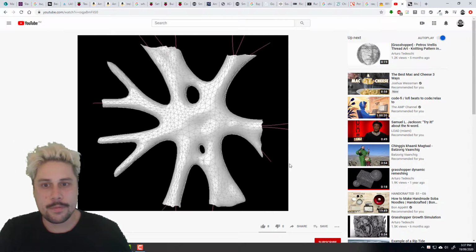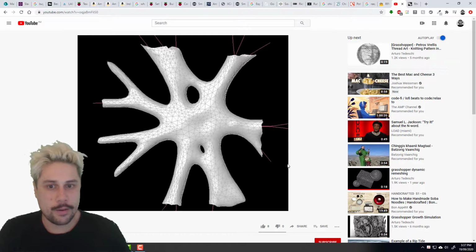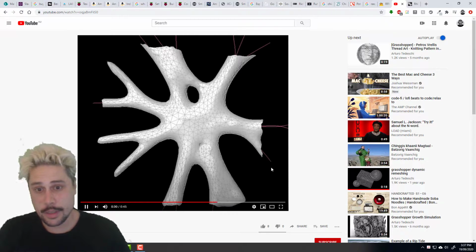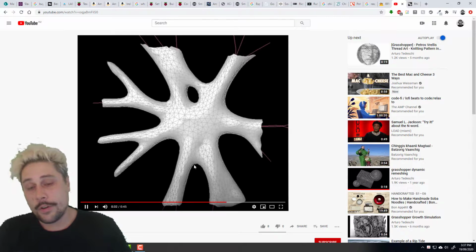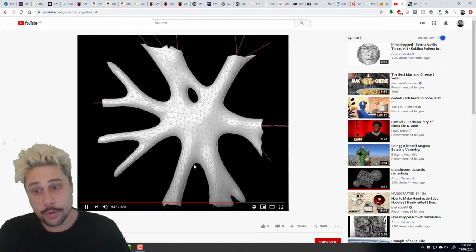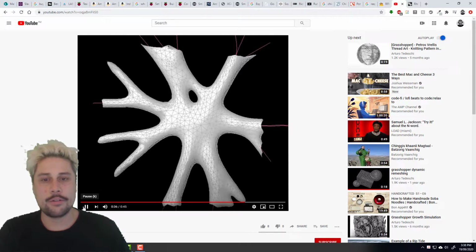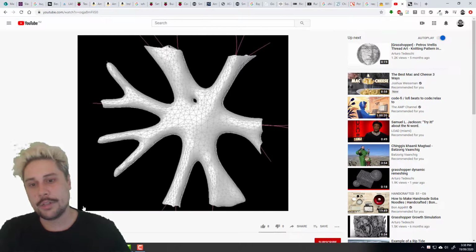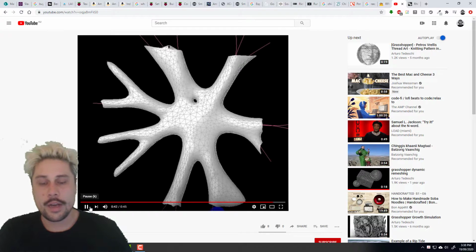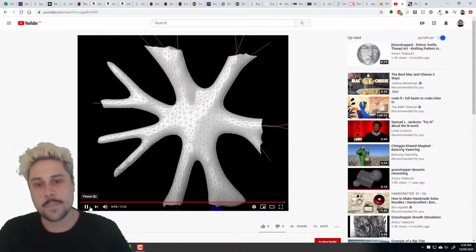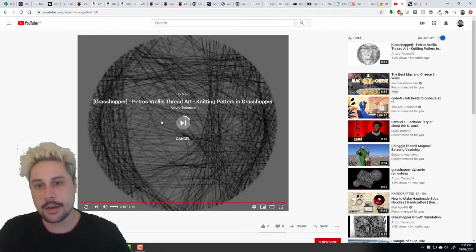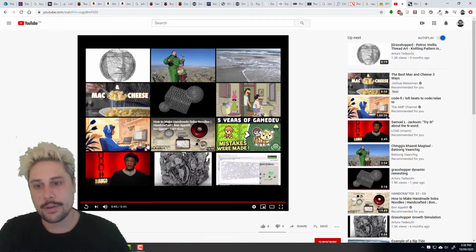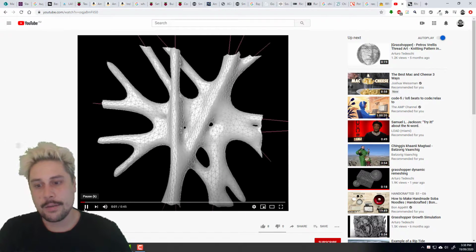So I thought I'd show you how this is built and how you can achieve this in Grasshopper using, firstly, the plugin called Cocoon, which is great for generating metaball geometry. Then we're going to put it into Mesh Machine, which is like a subset of Kangaroo, afterwards to remesh it to make it look a bit better.